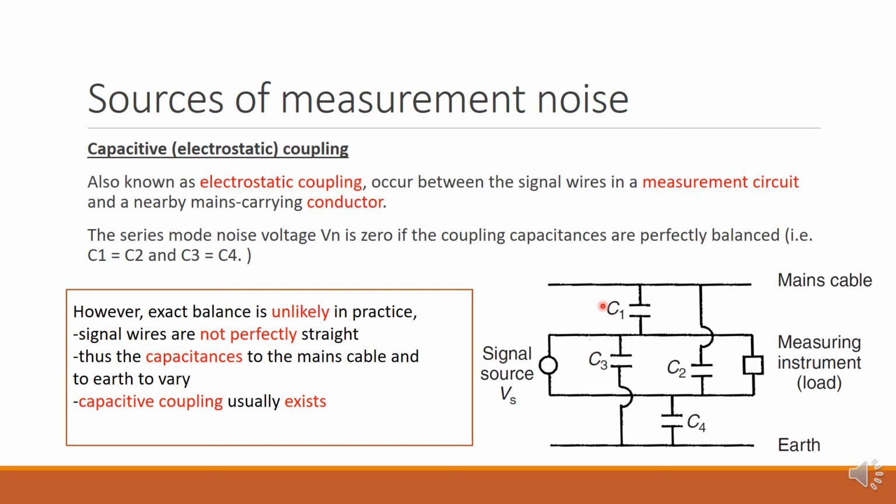For inductive coupling, your cables are active; there is a current flowing. Now for capacitive coupling, your signal source has voltage and current flowing in your circuit. These main cables have no circuit flow, no current flowing, and earth has no current flowing.